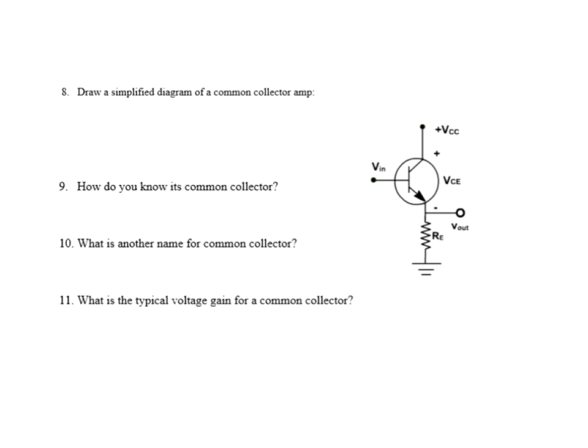All right, how about another amplifier that you've talked about, or switch? A common collector. Okay, now in addition to the power supply, where is the input being fed into this? The input is on the base. The output is off of the emitter. Anytime you have the input on the base and the output off of the emitter, it's got to be a common collector. So a common collector has the input on the base. They will always have the input on the base, and the output signal always comes off of the emitter.